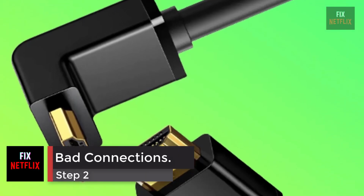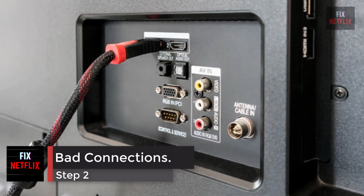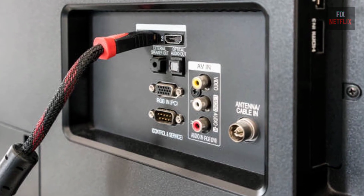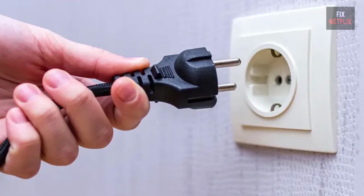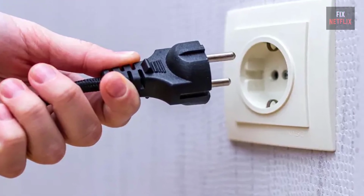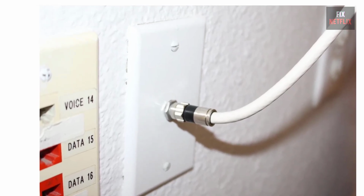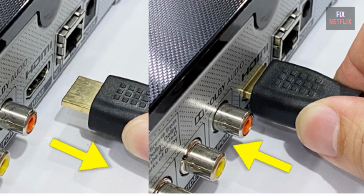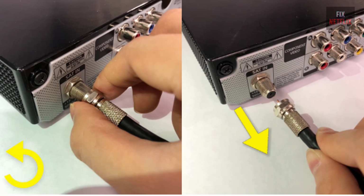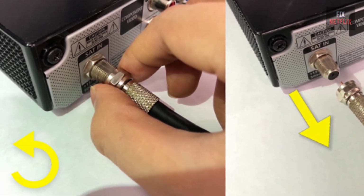Step 2. Bad connections. The HDMI inputs can have problems that will interrupt the video signal while still allowing audio to function. There are two main points of failure: the input sockets and the cables. First, unplug and re-plug each HDMI cable at both ends, the TV end and the other connected device. Do this for every device that is connected to your TV.